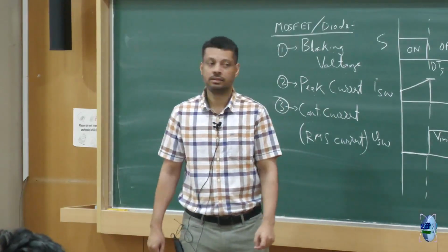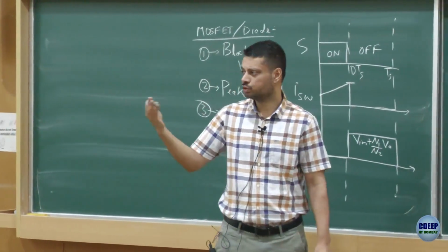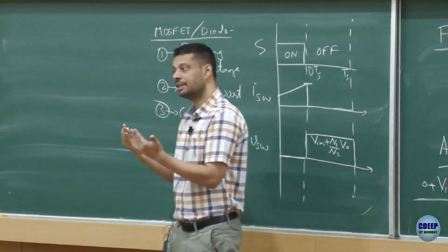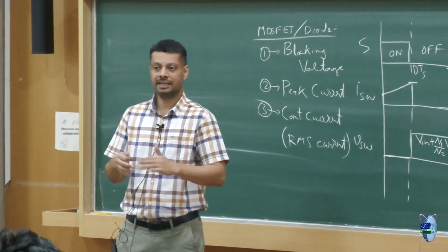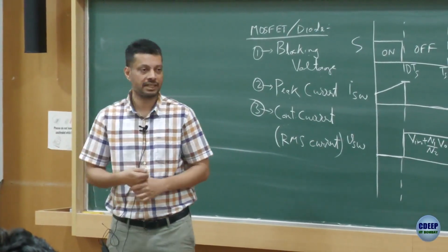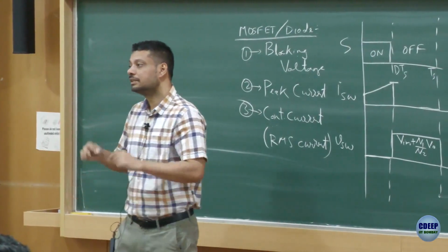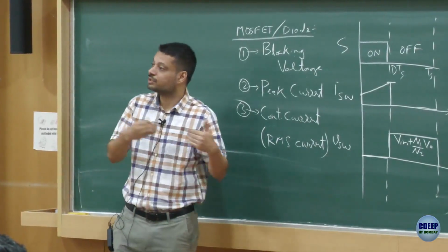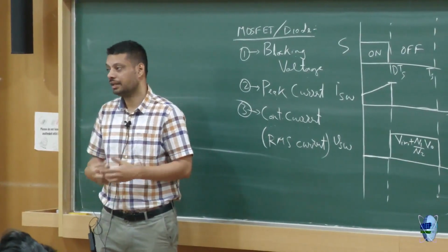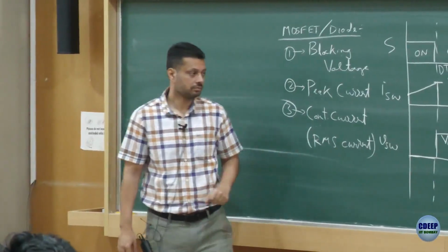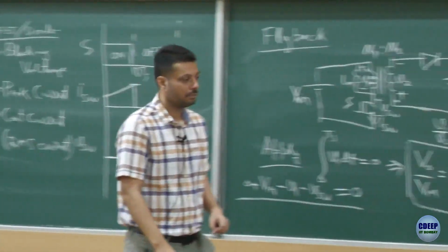Any question? Yeah, somebody said switching frequency. Of course switching frequency will matter, but if you open a MOSFET data sheet, have you seen one? Once you go back, just Google any MOSFET, TI MOSFET or any MOSFET data sheet. Specifically, they will not say this MOSFET is designed for this switching frequency. You have to decide which frequency you want to use the particular MOSFET for in your application, and you decide it based on the losses. So that indirectly plays a role here. That is level 2, not level 1. Level 1 is these 3 basic things in deciding a MOSFET.